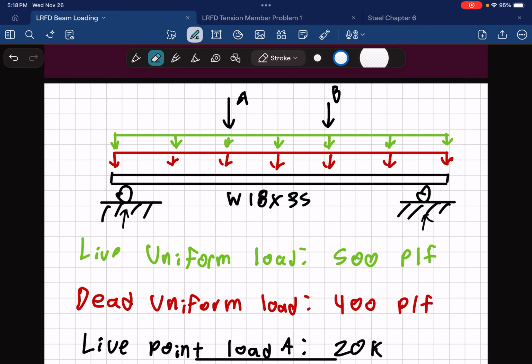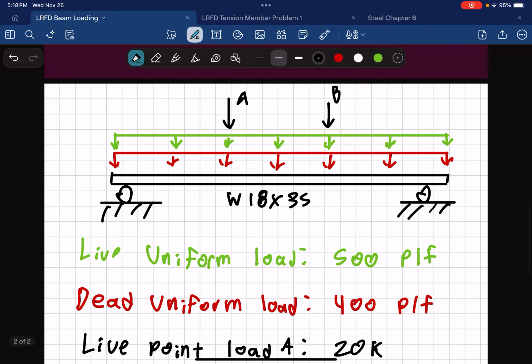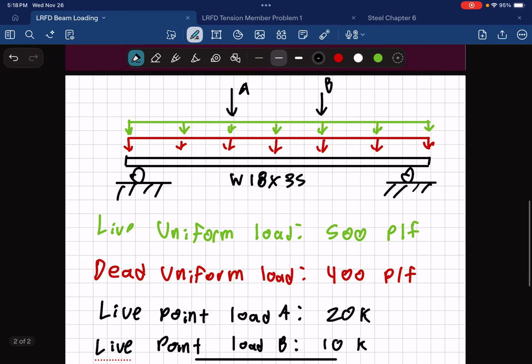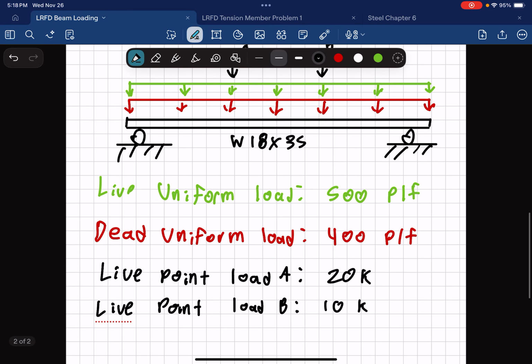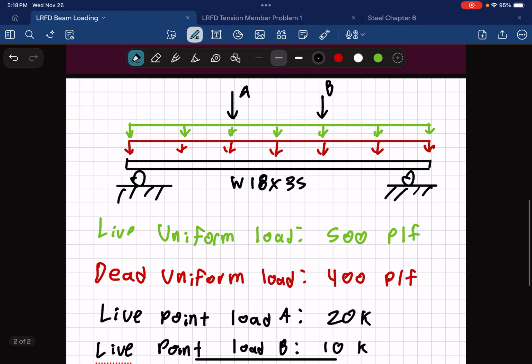Now when we're talking about beam analysis, you may say in terms of loading, the main thing that we want to figure out is how much load is actually being applied to the beam at first, and you're actually correct on this. But as you may remember with LRFD, we have some load cases and load factors to deal with. Previously, when you looked at LRFD loading, you may have said, well, there's 5 equations, I'm going to have to go through all of them and it takes me a ton of time.